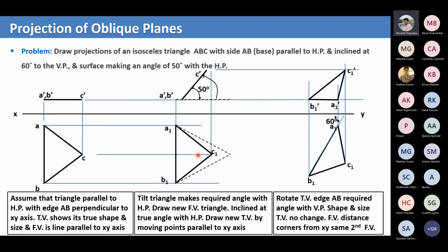So taking this, we proceed further. After this point, we don't need this anymore, because these are the true shapes, true heights, and true sides of the triangle. We take this and we proceed. So when you have these projections here and we have proceeded from this point, this is already having this 50 degrees in it.